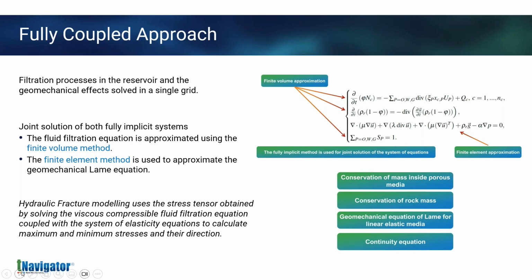In the first line, you have the conservation of rock mass as well, and you have a geomechanics equation, the Navier equation, in linear elastic media with displacement factors. And of course, we have the conservation of mass of the fluid inside the porous media. We have different boundary conditions. We have Dirichlet boundary conditions, Neumann boundary conditions. We can use stress and strain boundary conditions to accommodate the tectonic components of our reservoir.